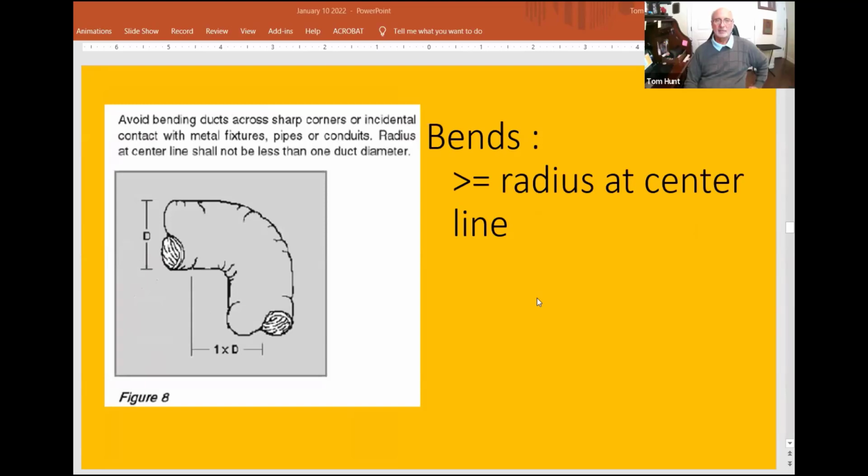Oh, your bends. Yes. That's hard to achieve without a 90-degree mechanical elbow. I've yet to see that without the elbow. I have seen some come in, put elbows on the end of metal duct and then drop straight down into their lay-in ceiling with it. But I've never seen flex duct turned at a true 90-degree radius like that without a mechanical elbow.